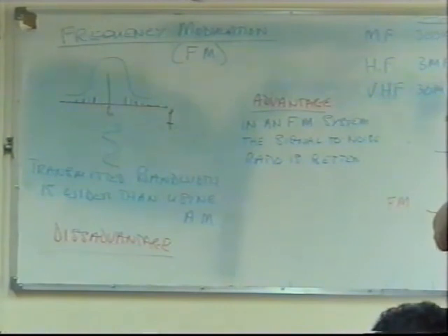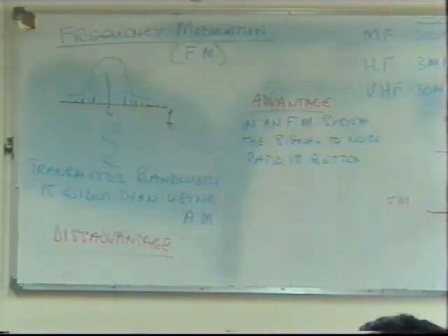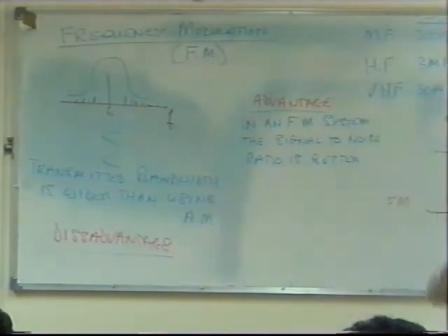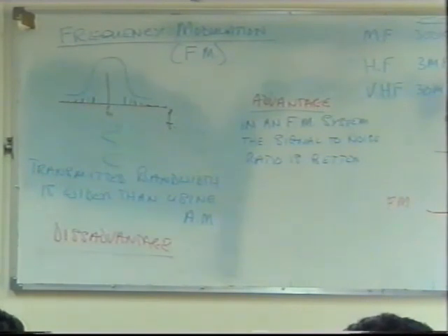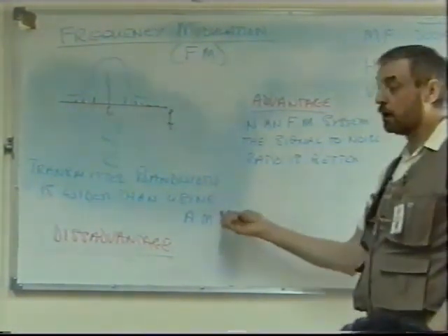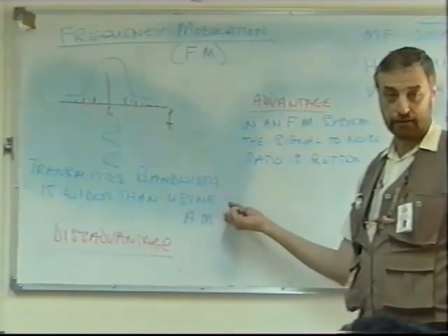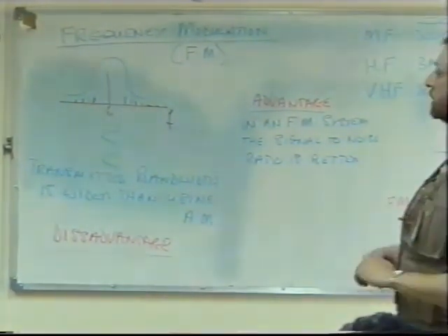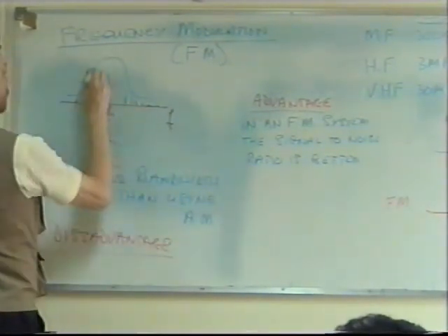Because it gives us more channels, narrower band. But with FM, it's a wider band. We can use it on VHF and we can use it on UHF, but we wouldn't use it on these two. Do you see the reason? The FM has a wide bandwidth. Advantage, not disadvantage. No. This is the bandwidth of a single channel. When I say wide bandwidth, I'm talking about the bandwidth of one channel.